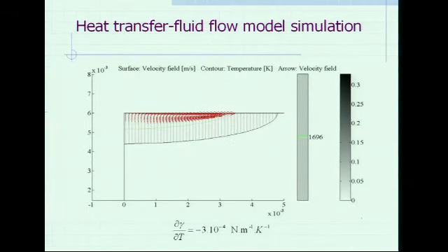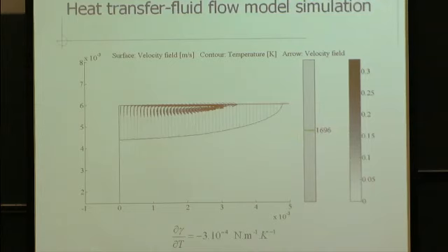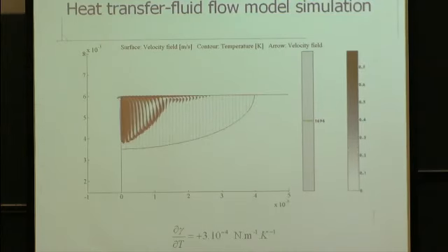So basically we use this negative coefficient for the surface tension, and the motion of the fluid is occurring along the top surface, turning here and then going slowly to the center, decreasing the velocity, and the velocity is higher in this area. Now if I change, for example, the coefficient, it becomes positive. If we have a high sulfur content, we can get this sort of shape. So it will affect a lot the whirlpool size, and also the temperature field inside.